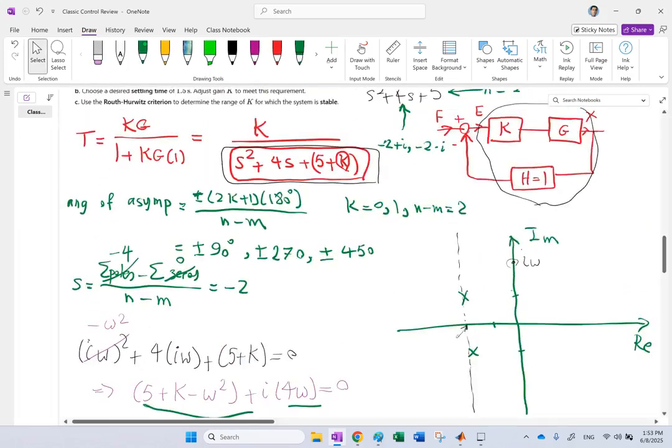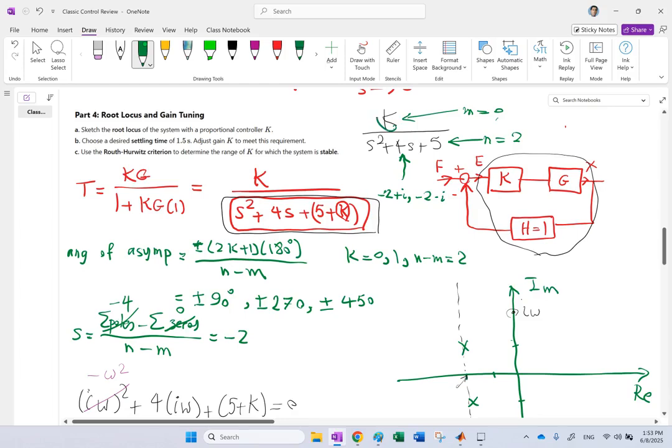And you know that in a root locus, this gain k is always positive. The fact that it says for k of negative 5 you hit here means there is no intersection with the imaginary axis. So the root locus in this system will never hit the imaginary axis.